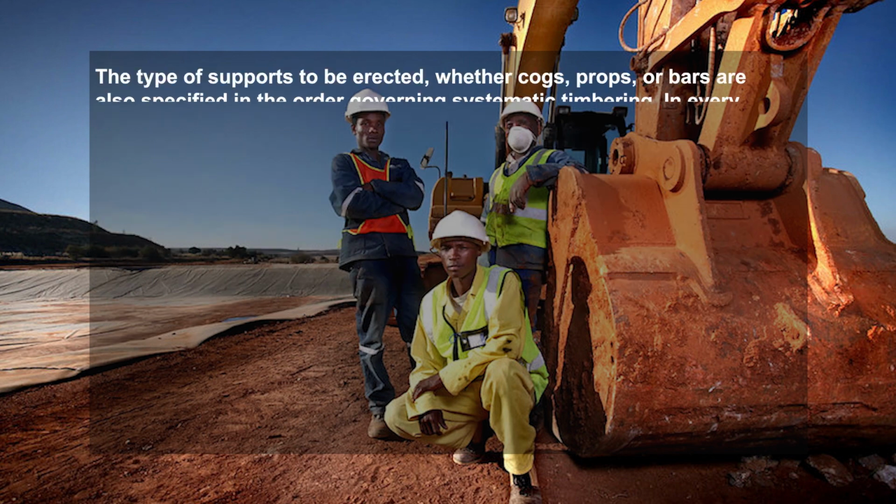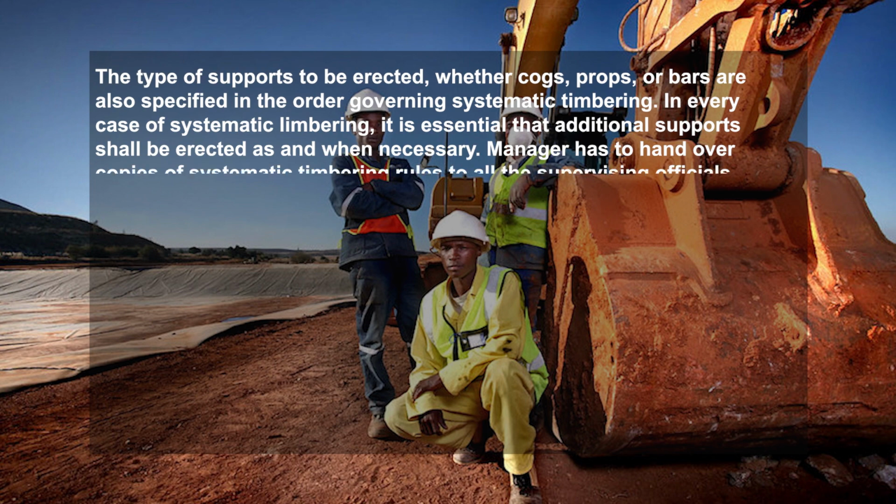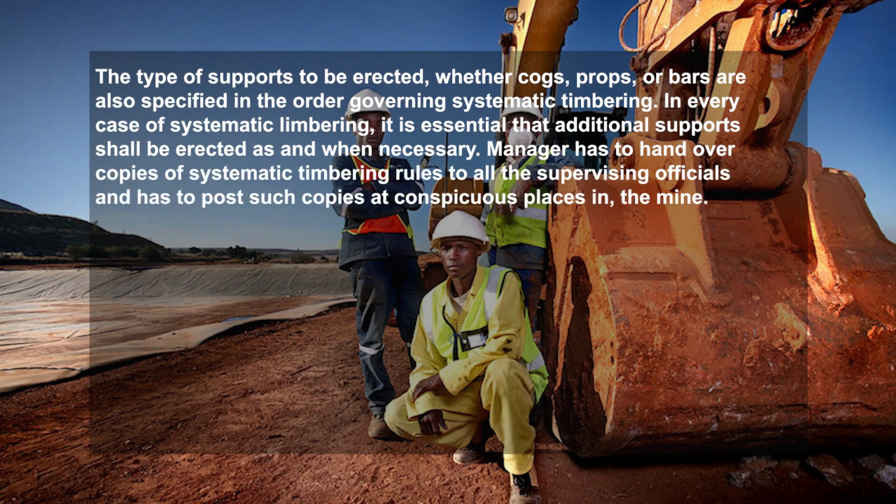The type of support to be erected, whether caulk, props or bar, is also specified in the order governing systematic timbering. In every case of systematic timbering, it is essential that additional support shall be erected as and when necessary. The manager has to hand over copies of the systematic timbering rules to all the supervising officials and has to post such copies at conspicuous places in the mine.